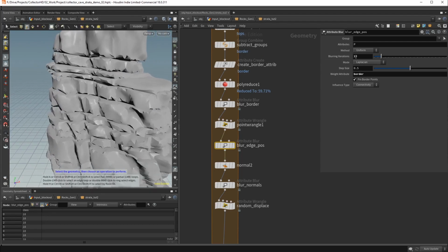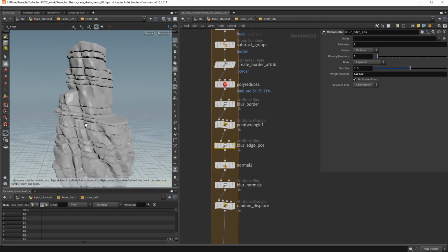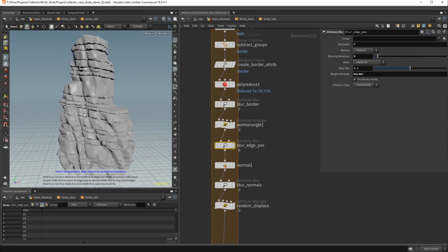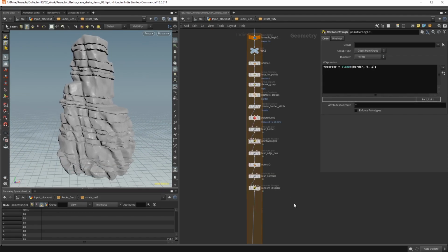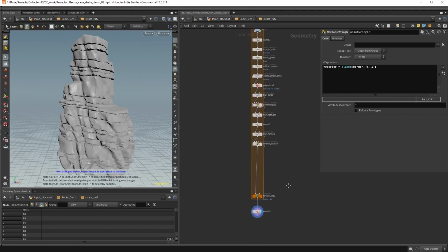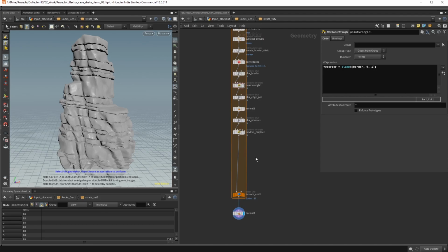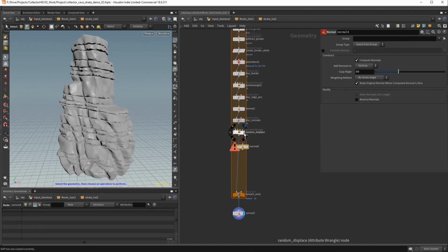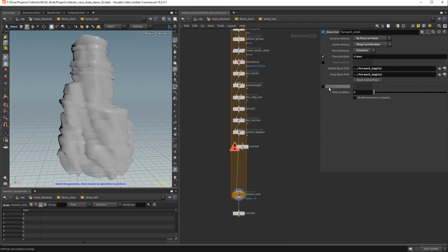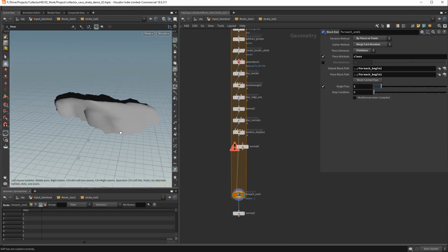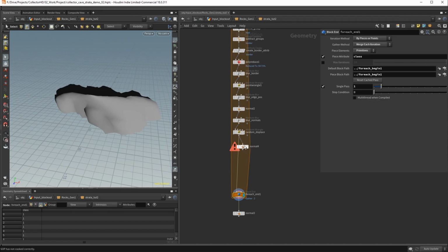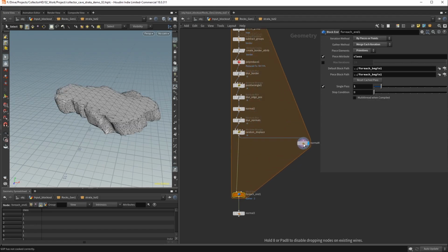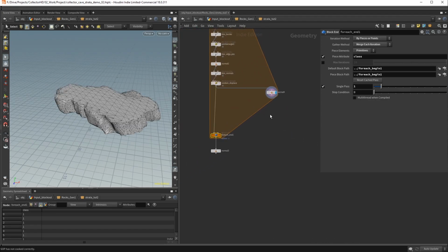What we want to do next is add even more erosion, some kind of chipping of smaller pieces, like if the layers were cracked and some of the smaller pieces went missing. We start by adding back normals to our geometry. Just put back the single pass mode to work with one piece. Make some more room.